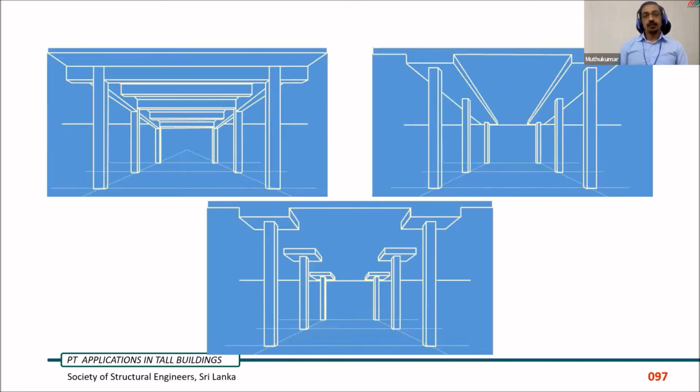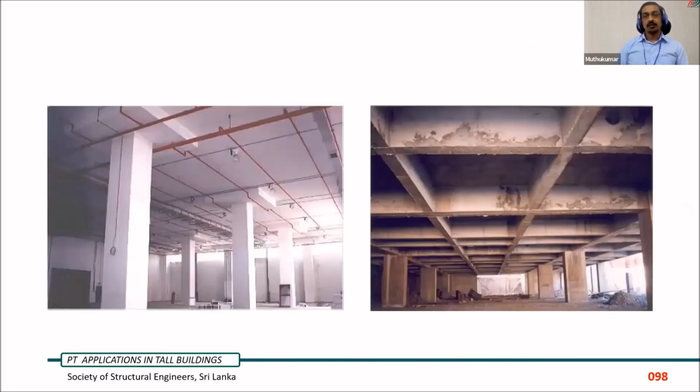In high-rise buildings, we choose 3 to 4 standard floor systems. One is two-way beam slab, banded beam and slabs, and flat slabs. So two-way beams will be used when the loading is too high as well as when vibration needs to be under control. We try to choose that option. Otherwise, PT flat slab provides much flexibility for services.